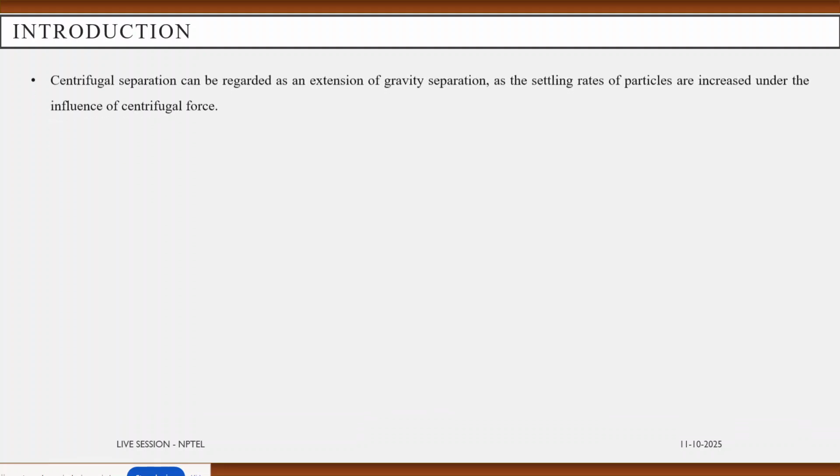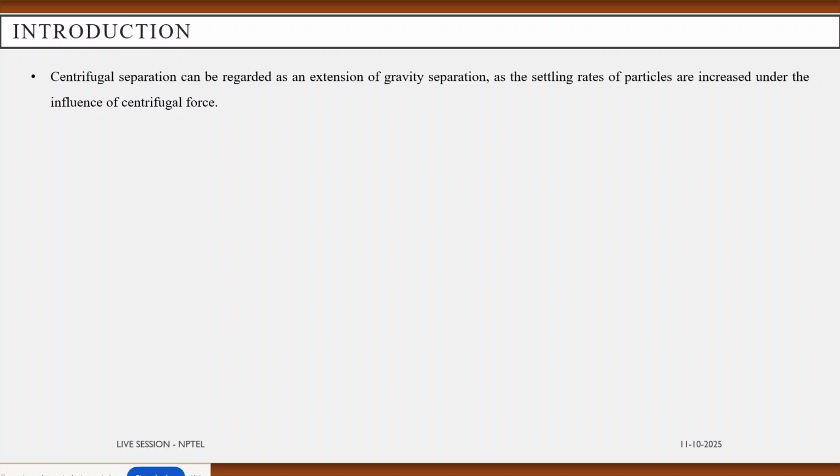This centrifugal separation process can be regarded as an extension of the gravity separation process, where the settling rate of the particles is improved under the influence of the centrifugal force.